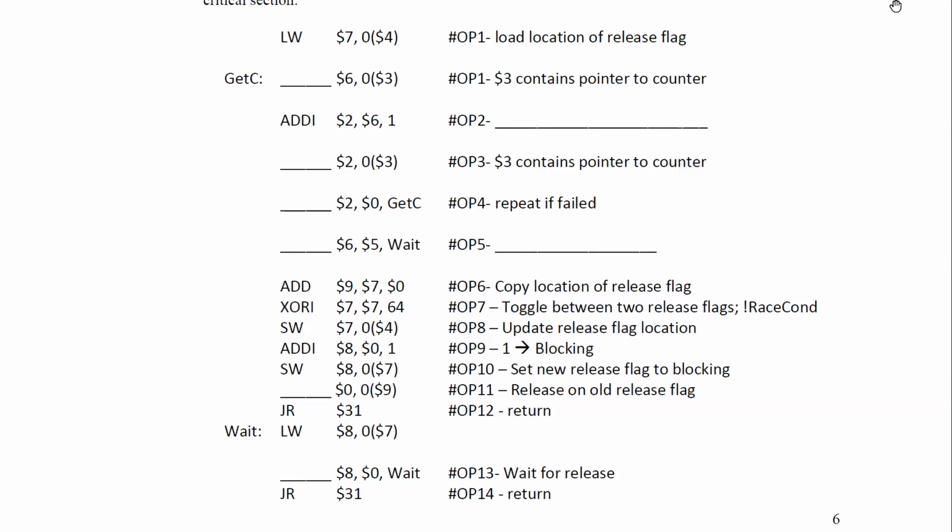So the only thing I need to worry about here would be race conditions, other sorts of logic errors. This isn't an architectural fundamental problem with the ISA or the notion of atomicity. This is just, is my code right? So if I have constructed my code so that only one of the people is doing this, then the atomicity is natural. A store happens or it doesn't. But a read, a modification, and a write does not naturally all happen at once. That's what you need actual architectural support for. So anytime you have a read, modify, write pattern.